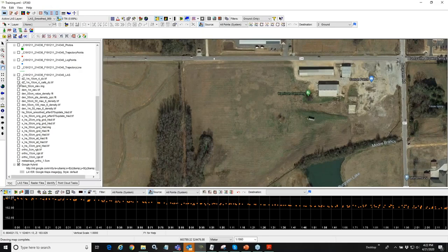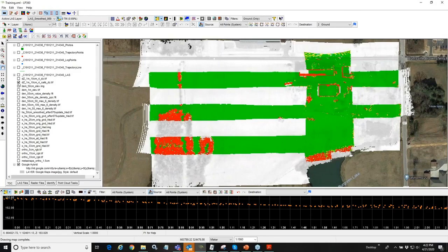A DZ image is a very effective tool for looking at how well your flight line to flight line are matching. If you're familiar with calibrating airborne LIDARs, terrain match workflows, things like that, you'll be familiar with these. Basically, the way you interpret this is each of those pixels, if it's green, it means, I think in this case, I used 9 centimeters, so the ASPRS standard. So it's well within that ASPRS standard for